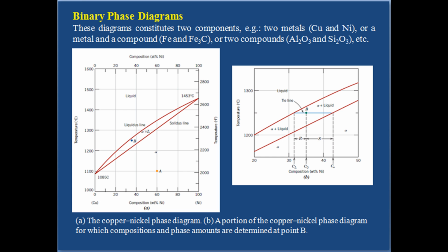Many microstructures develop from phase transformation, the changes that occur when the temperature is altered, typically upon cooling. This may involve the transition from one phase to another, or the appearance or disappearance of a phase. Binary phase diagrams are helpful in predicting phase transformation and resulting microstructures, which may have equilibrium or non-equilibrium character. Now we are going to move further with our next discussion regarding the binary isomorphous system.